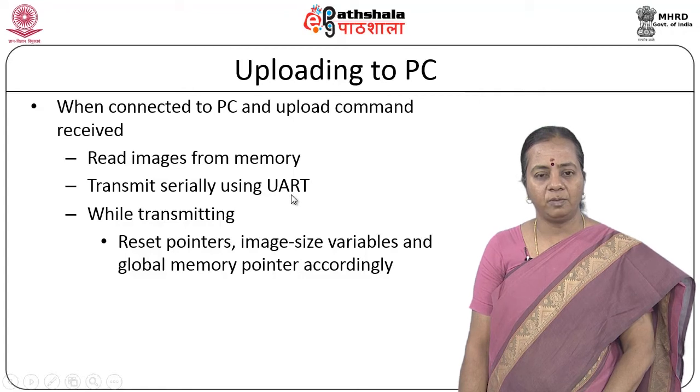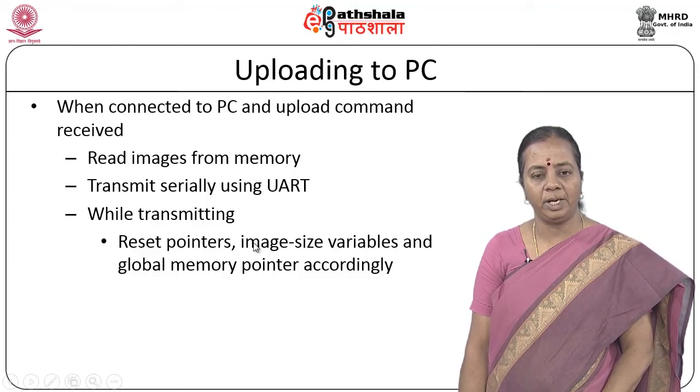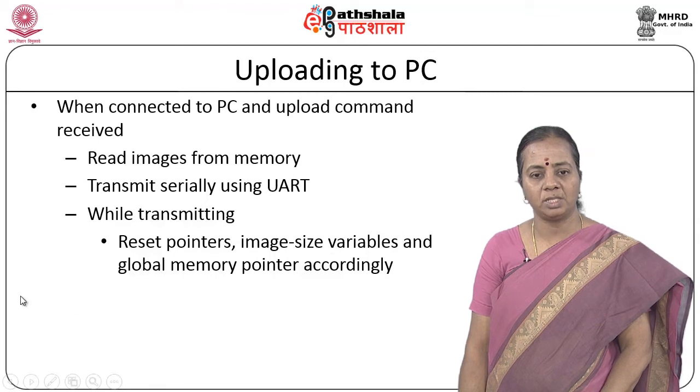We use that particular port, the RS-232 port, connected along with a line driver, so that it will transmit the data towards your PC and you can store it. While transmitting, we have to reset the pointers, the image size variables, as well as the global memory pointer accordingly.